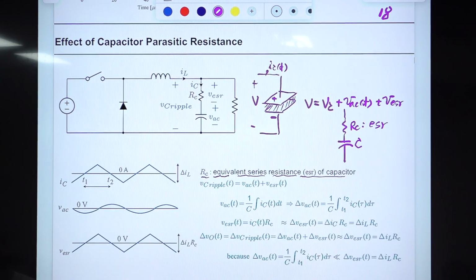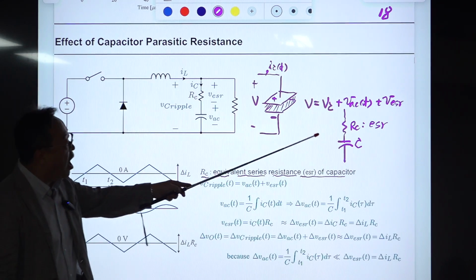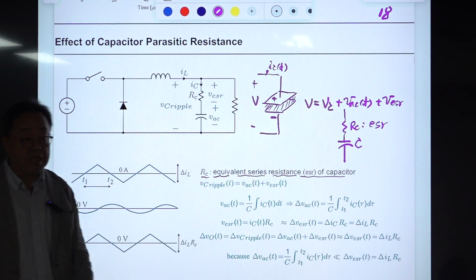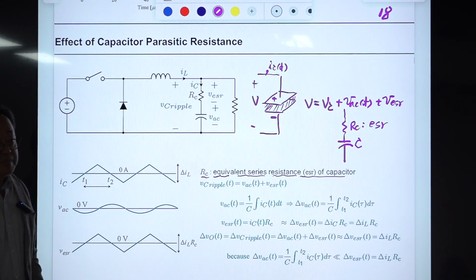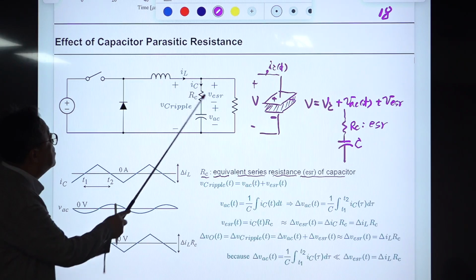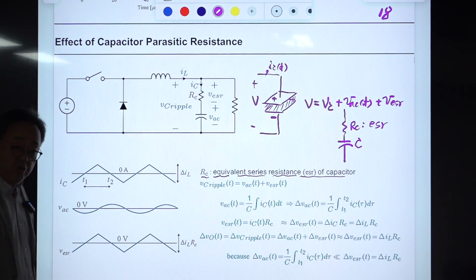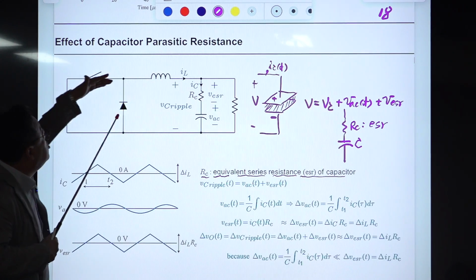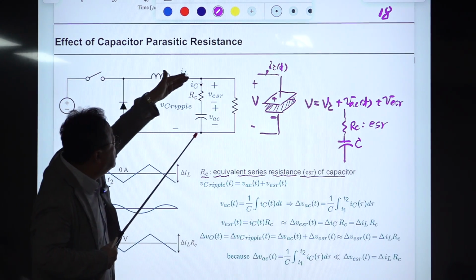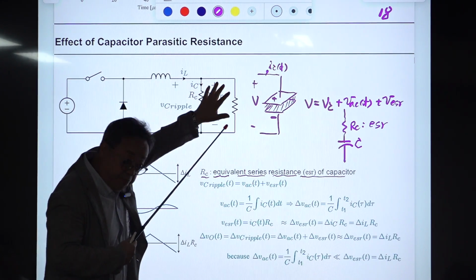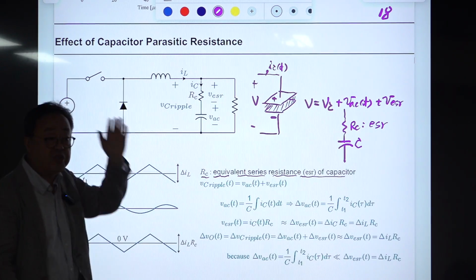And the more important aspect is this combination of this R, C creates what? Pole or zero. It creates a zero. Okay, because at that frequency, this impedance becomes zero. That means whatever voltage appears here, this voltage division is zero. So output becomes zero. That is the definition of the zero.